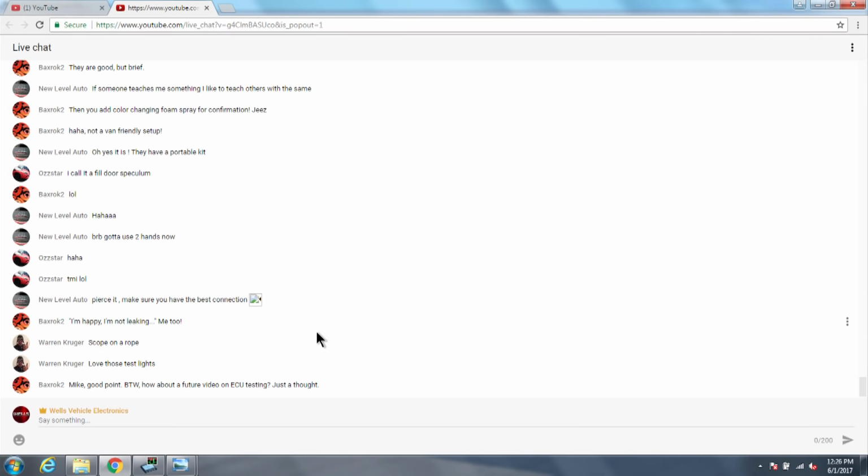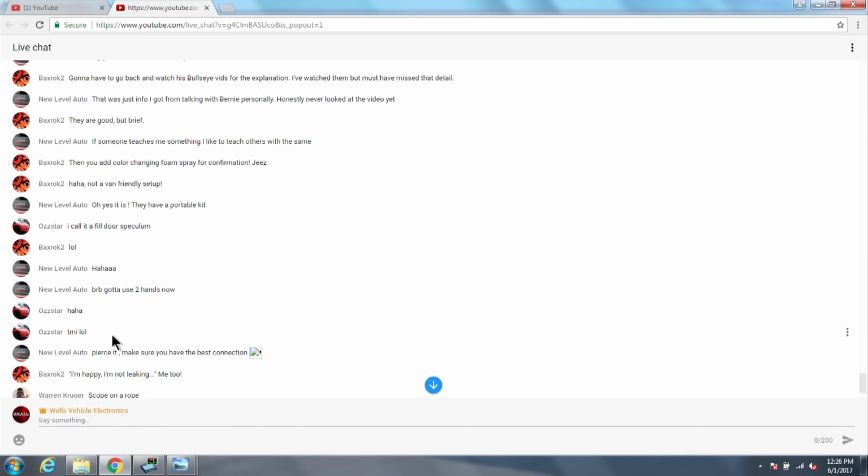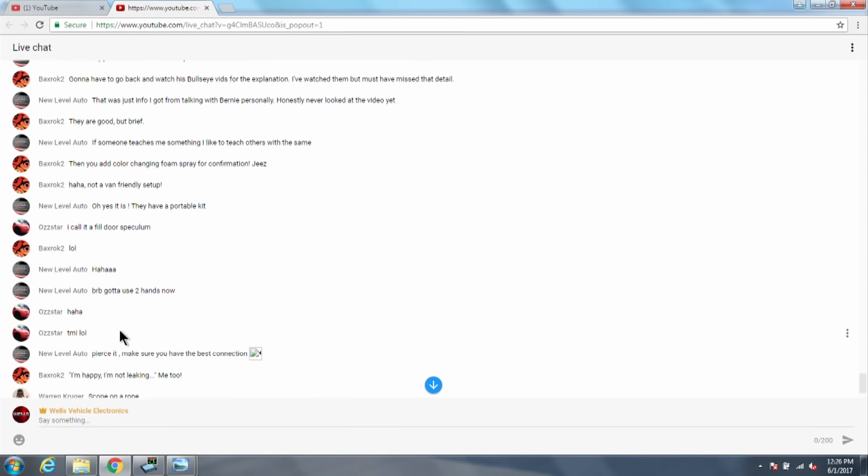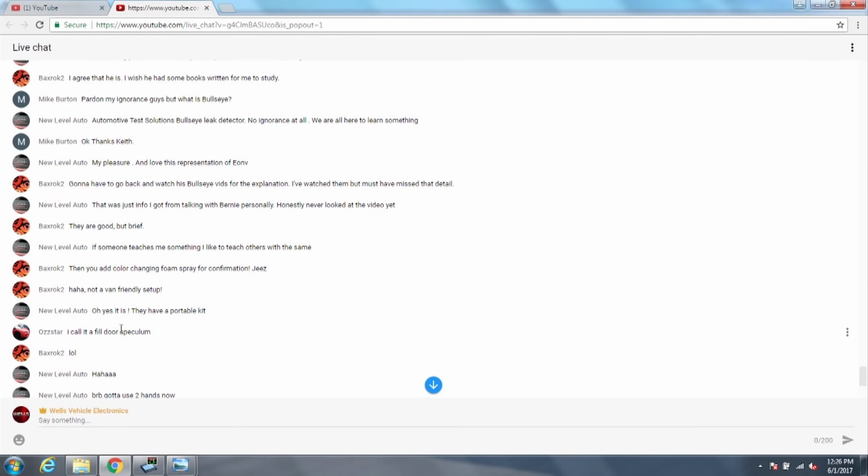I'm just going to take a quick scan through the comments. Oh, New Level Auto. You're saying pierce it, make sure you have the best connection. I hope that's a sarcastic little image after that. My laptop here is not loading it. I don't like to pierce connections. Unless I have to, it can create problems. I like to back probe. That's what I like to do, or wire in some sort of T connection where I can get into it.